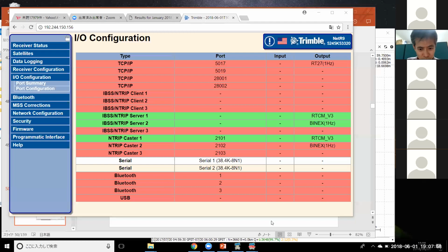Sometimes we do not get DOP from RNX files using RTK Pro. What is the reason behind? Sometimes we don't get DOP. Maybe too small a number of satellites? Under 4?